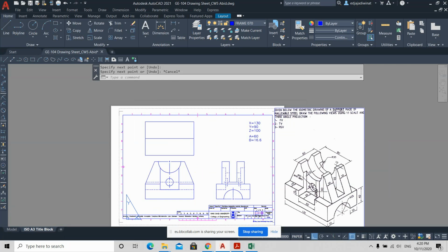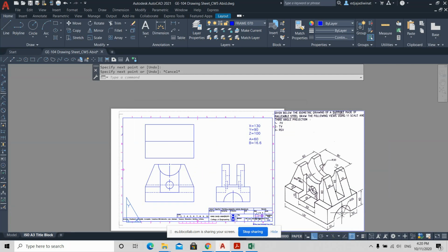And then from here, I'll make the tunnel. The tunnel will be using offset again. The offset is 25 because the radius is 25. Offset here, this up or down.